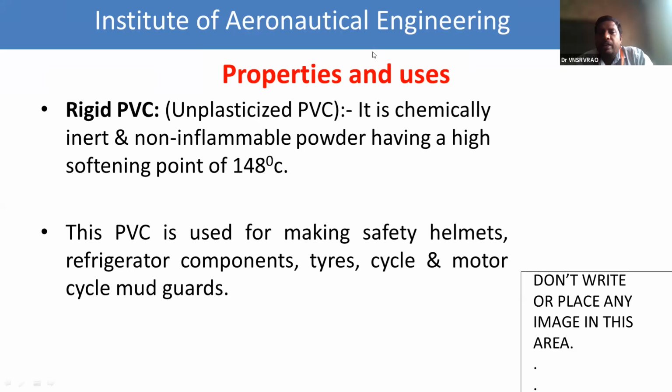It is non-inflammable. Unplasticized PVC is rigid PVC. Why does this PVC get such a nature? Because of the absence of plasticizers. Without plasticizers, the plastic is not applicable to molding purposes and it becomes rigid in nature.